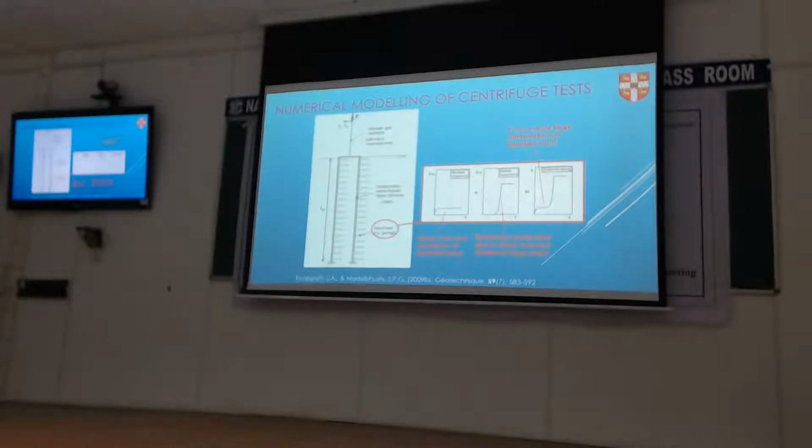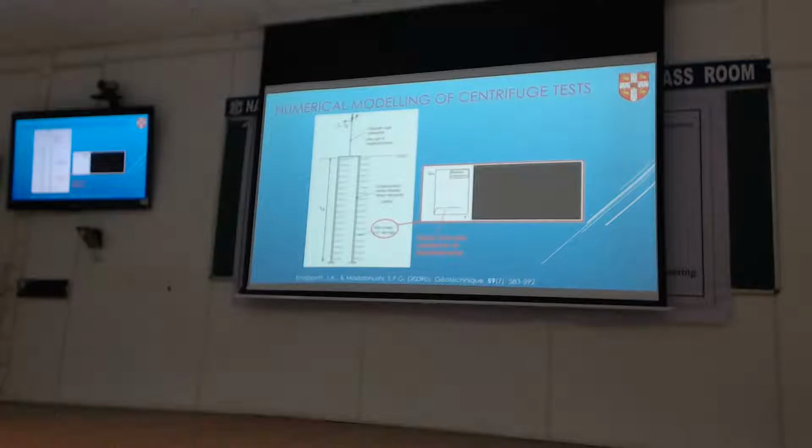And when we are applying either the buckling of the pile or pile group in this case, we can have lots and lots of springs on each of the piles and apply the axial load and see what it does. Equally, you can do the same thing if I'm applying purely lateral load and try to do a pushover analysis of the pile group in liquefied soil. As long as I've got this, I'm in business. Either using complicated finite element code, or I can write one in MATLAB in about half an hour. Either way, they'll do the same thing.